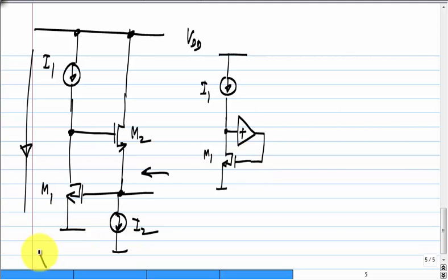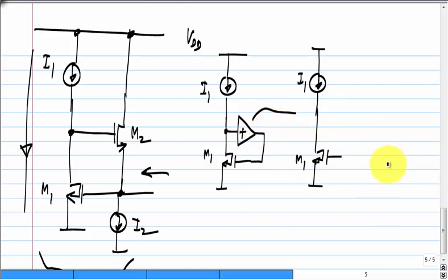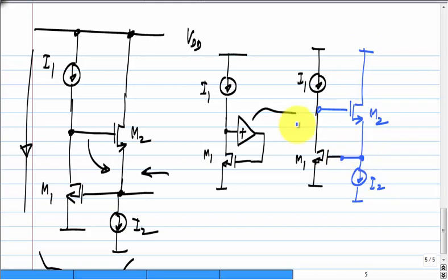Now, you can think of this whole circuit as again centered around M1, where you are trying to bias M1. And what is the stage you use for positive incremental gain? What is M2 from here to there? What kind of stage is that? It is a source follower. So, you can think of M2 as implementing a source follower, and you use that to bias M1.